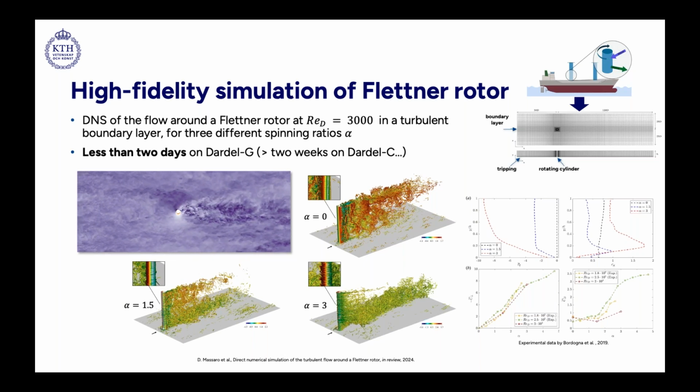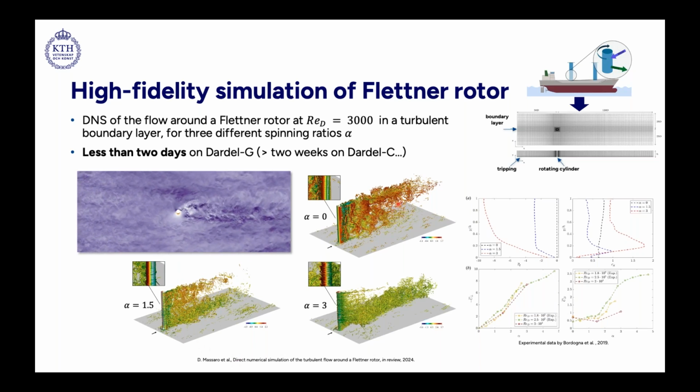So what we use this for is that we have studied a lot of different rotation speeds alpha for the cylinder and see how the wake goes from stationary to a bit more curved, which is an indication of getting this lift that will increase and act as a wind sail. And we have also compared this against experiment, and it's very nice to see that it agrees pretty well when it comes to this lift generation compared to wind tunnel experiments for a similar setup.